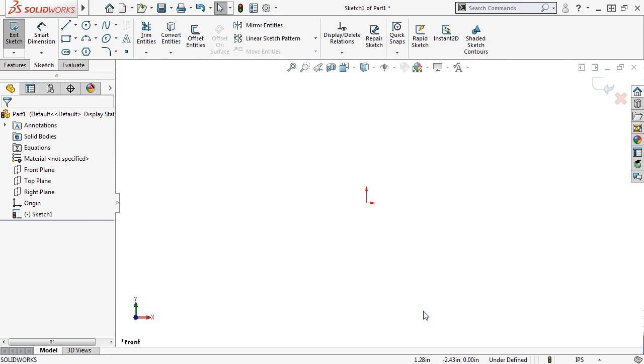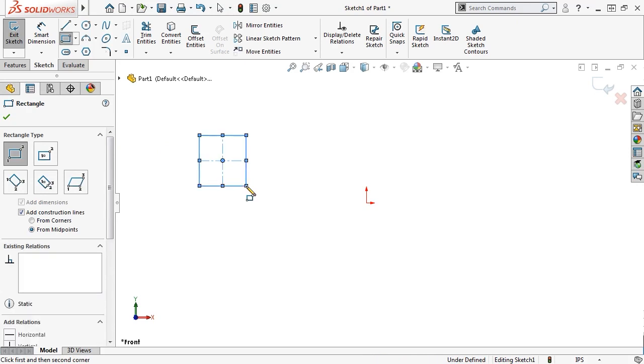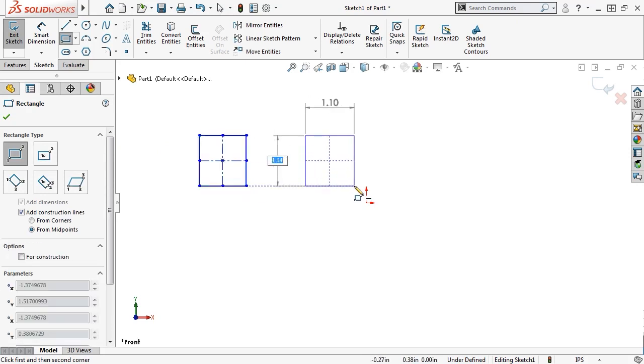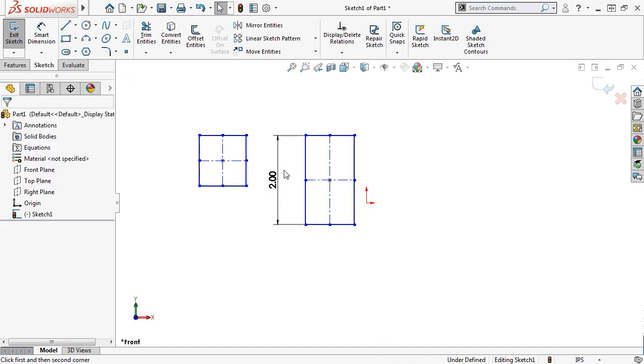Instead, with the setting turned on, notice that if I sketch a rectangle, the dimensions still appear. But if I click to finish, no dimensions are created. I'll sketch another rectangle. And if I instead type in values from my keyboard and press the Enter key on the keyboard, the dimensions are added to the sketch. Numeric sketch input can often save you time in defining and dimensioning your sketches, so it's a good idea to take advantage of all the different settings and options available. But if you don't want to add dimensions, just click to sketch as normal.